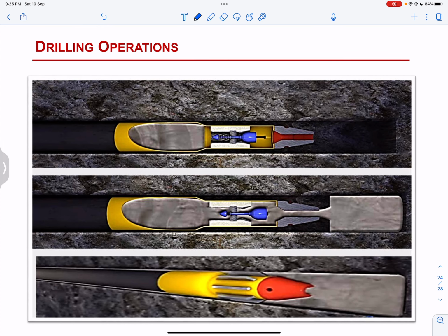Then a small diameter casing called production casing is installed. Throughout the total length of the well, the production casing is cemented and secured in place by pumping cement down through the end of the casing. Depending on regional geologic conditions, the cement is pumped around the outside casing wall to approximately 2,500 feet above the producing shale formation or to the surface. The cement creates a seal to ensure that formation fluids can only be produced via the production casing.